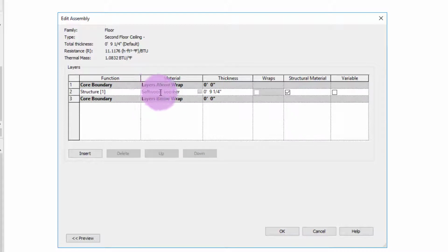And this softwood lumber, probably don't need 2x10s. Let's go ahead and put in some 2x8s, which is going to be 7 1/4. So put that at 7 1/4. But what I forgot on the last floor was to put drywall on the bottom of it, so you have drywall in your house. And even though it doesn't technically go out to the edge and all that, we could make a model or something.